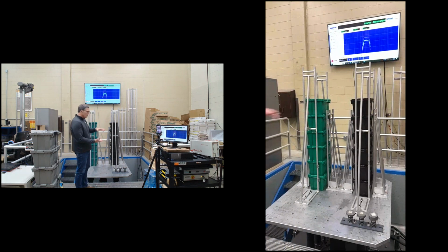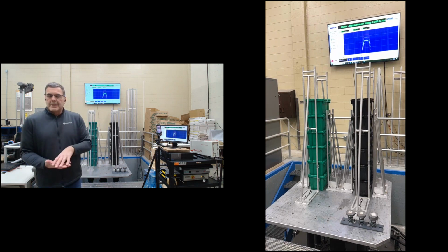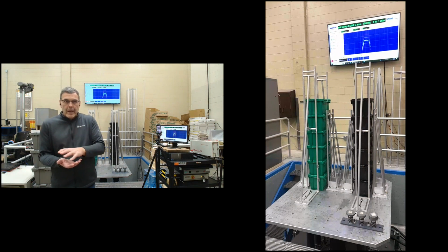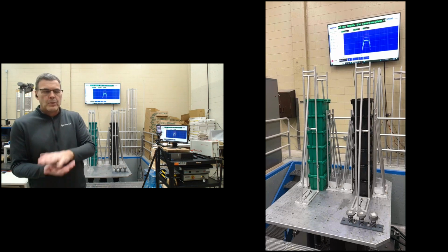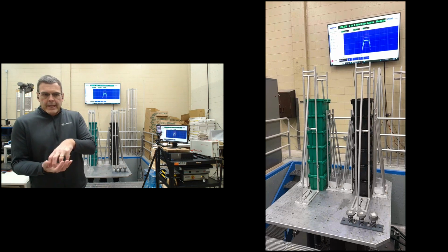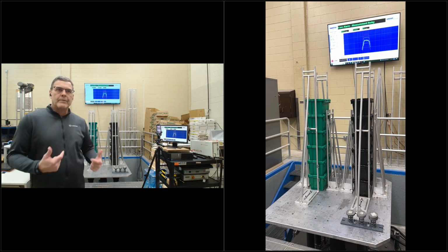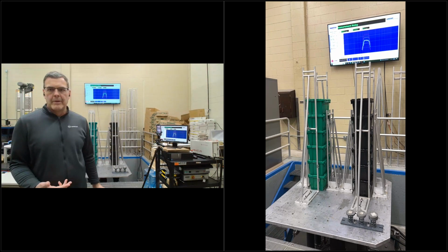If I had slow motion, you would see the stack is expanding and contracting almost like a spring itself. And so what happens is they're bouncing on top of each other. And if they bounce, depending on how heavy they are and how much separation and what the impact is between each other, it's what we call dynamic compression, where it's stressing the materials of the different layers. And so if you're testing individual packages, you're not accounting for that part of it.